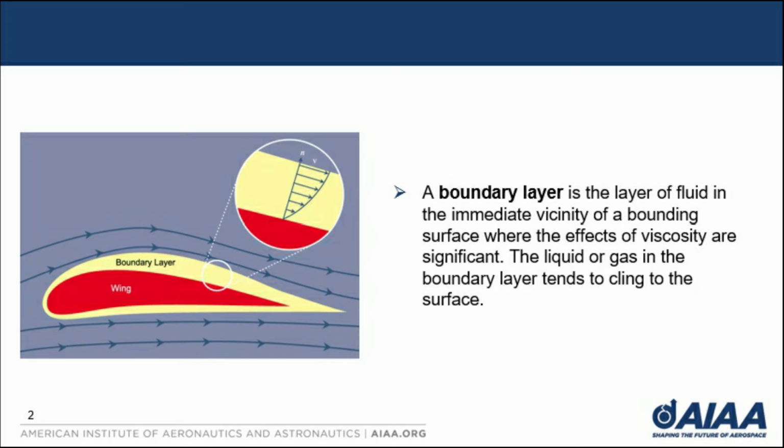With this in mind, when a fluid is analyzed considering the viscosity, we can express how the fluid will behave and predict things like turbulence. Focusing on this, we can start by giving a definition to our main theme, which is the boundary layer. To give a definition of the boundary layer, we first need to explain the behavior of the fluid near a surface. A viscous fluid will have some friction forces when the fluid passes through a surface. That is why exactly at this surface, the fluid will have a velocity of 0. The distance between the surface of velocity 0 and the start of the true speed velocity will be a small layer which will be named boundary layer.